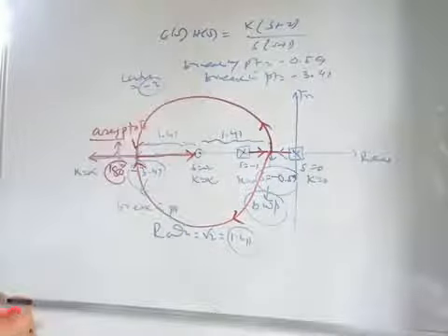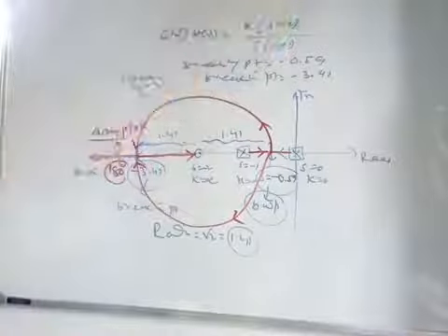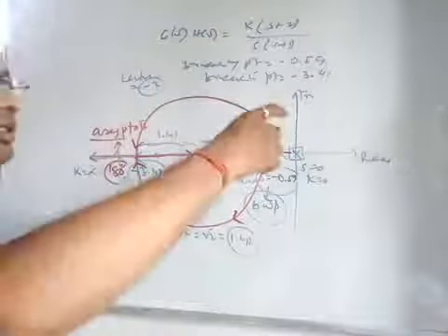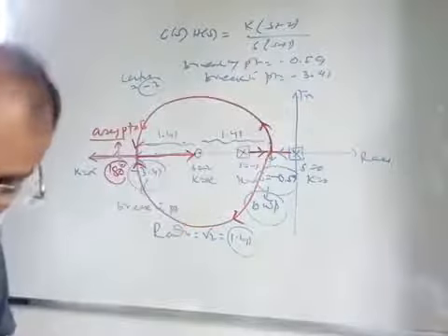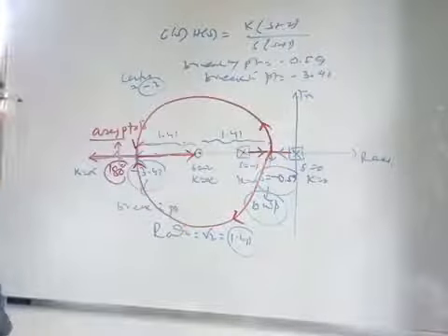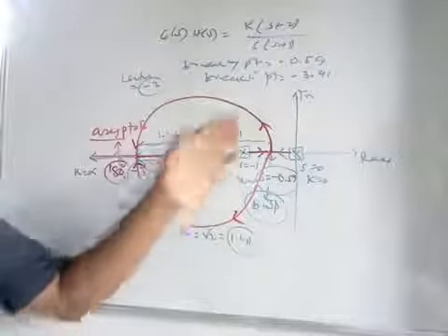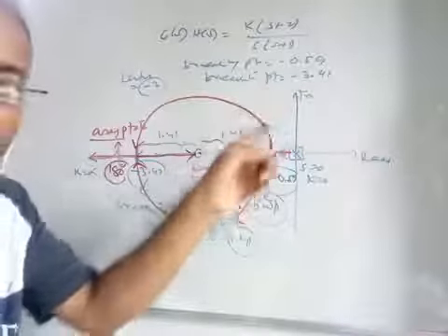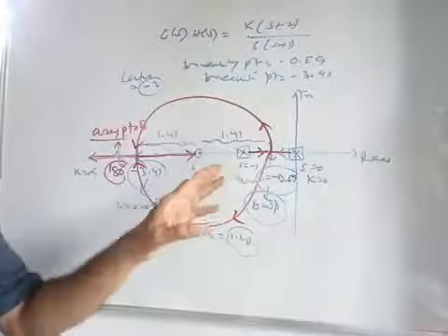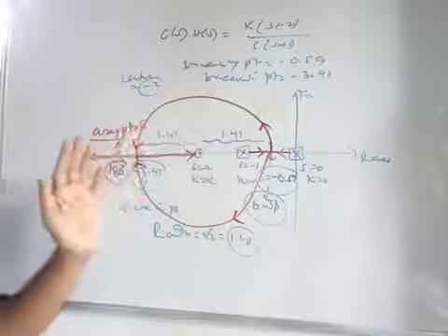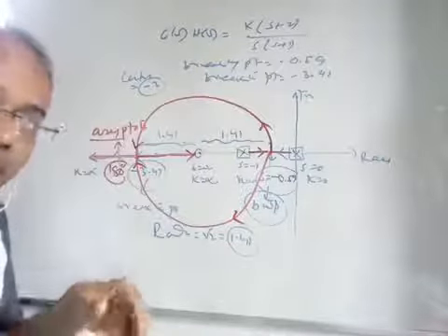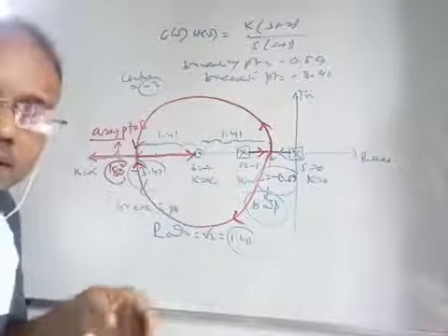If the system is like this, then that will be the root locus, and in that case you need not find the Routh array, because there is no chance of the root locus branch moving into the right half of the s-plane, where it would cross the imaginary axis. So this is the example where you can see both breakaway points and break-in points existing simultaneously.